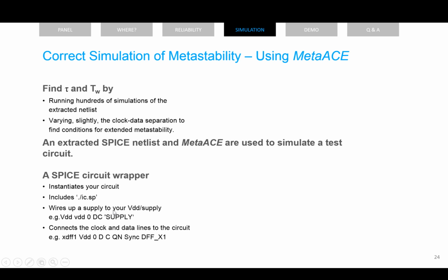The free version only limits you to 250 nodes that can be in the circuit to be analyzed. We found this is more than enough to simulate a reasonable synchronizer circuit with a C-only extraction, which we've also found is about 5 to 10% off of a fully extracted netlist in practice. So it gives you a pretty good idea of the ultimate performance, but with a significantly reduced runtime due to the much smaller circuit size that needs to be simulated.